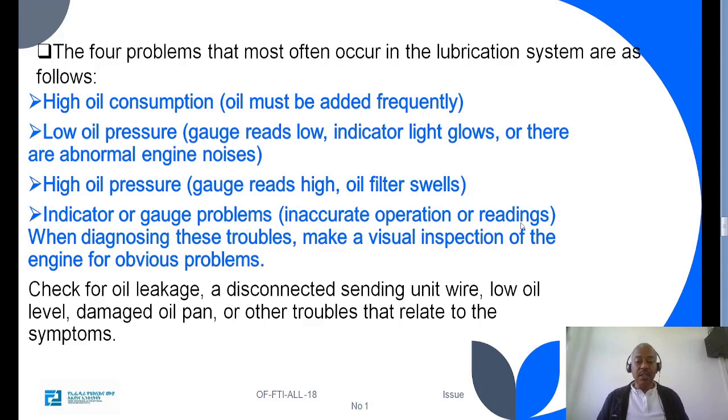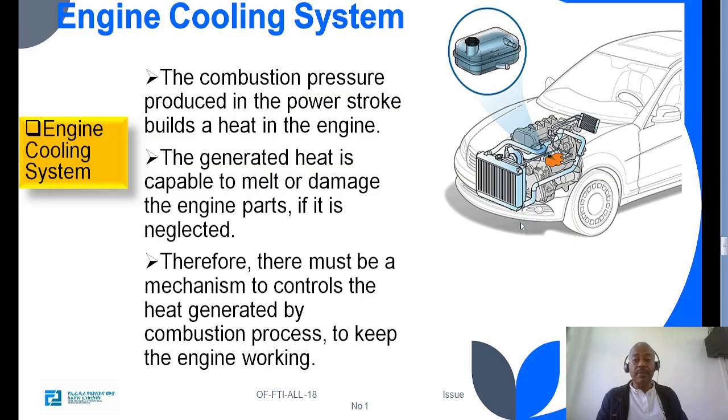When diagnosing this trouble, make a visual inspection of the engine for obvious problems. Check for oil leakage, a disconnected sending unit wire, low oil level, damaged oil pan, or other troubles that relate to the symptoms.